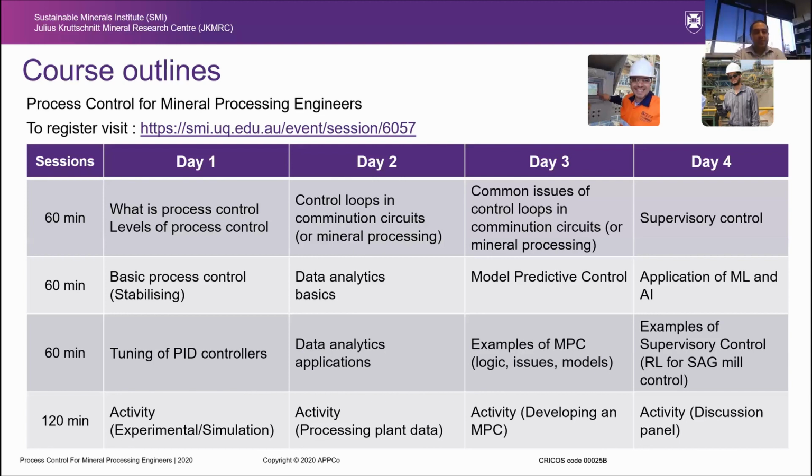So that's the conventional model predictive control that is in the market. There are groups that are actually doing that. Essentially, what they have done is, in many cases, they developed a linear response range for different processes. And then they use the live data to inform those models and do the prediction.